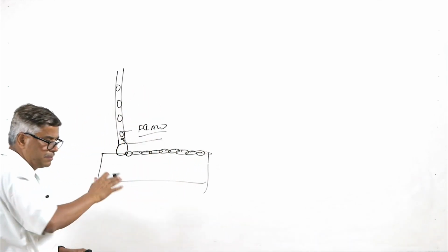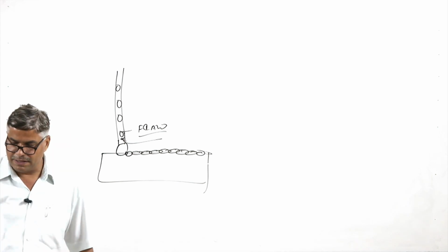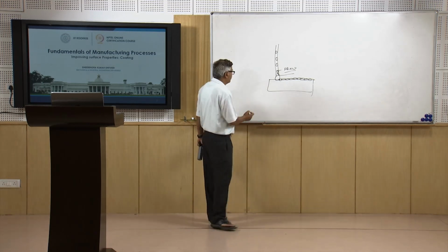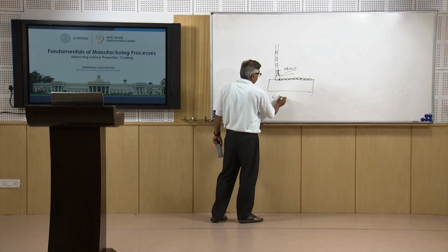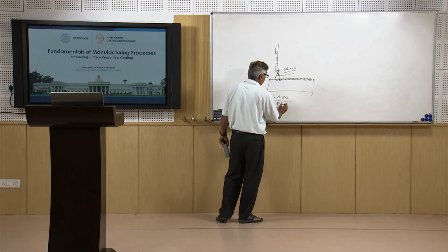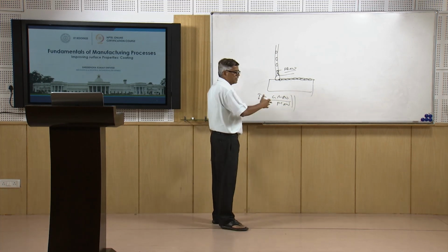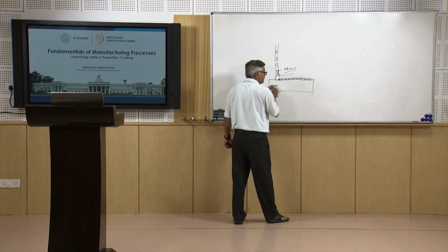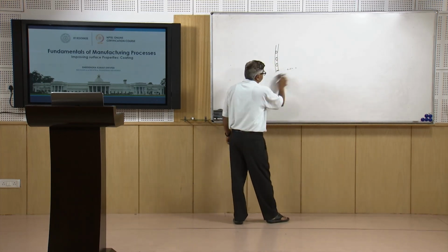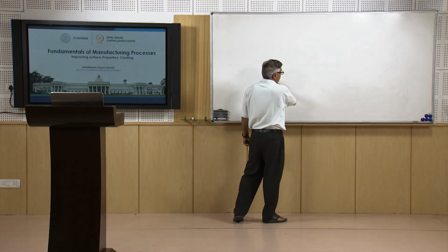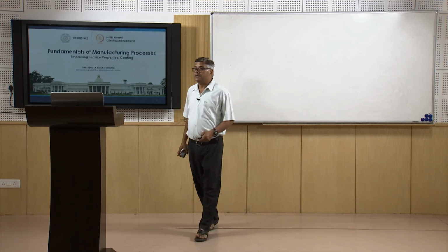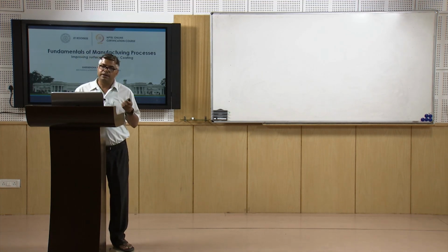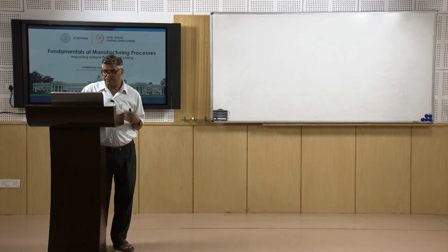Since it uses a consumable electrode fed continuously in the form of wire, larger amounts can be deposited in one go over a larger area. So, this is more like an industrial process, both GMAW as well as FCAW. For most industrial applications where consistent quality is needed and a lot of metal is to be deposited over larger areas, gas metal arc welding and FCAW processes are used. Different processes offer different extents of dilution and different levels of cleanliness of the weld bead being deposited.